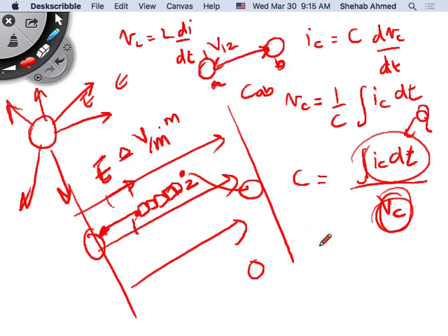How about if I am, let's say, a transformer terminals. These are two transformer terminals. This has a certain potential or charge. This has a certain potential. The voltage difference between those I can define as V12, for example. This V12 will correspond to a certain capacitance between these 2 points in space, right?